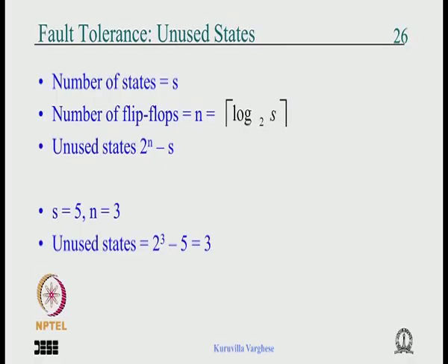It may not reap the benefits as you think. So let us come to the next issue, which has to do with the fault tolerance of the state machine. This is about the unused states. Suppose we have the number of states as S. Then we know the number of flip flops n is the ceiling of log S to the base 2.